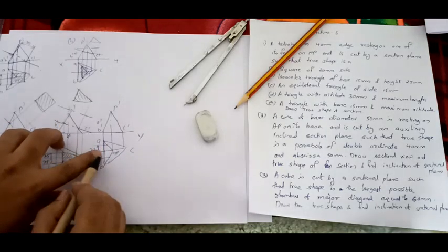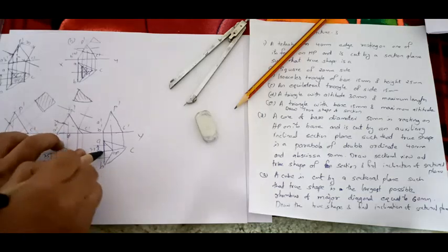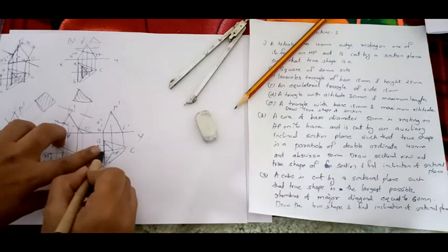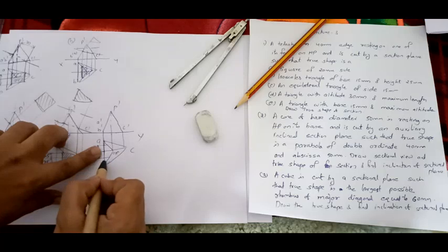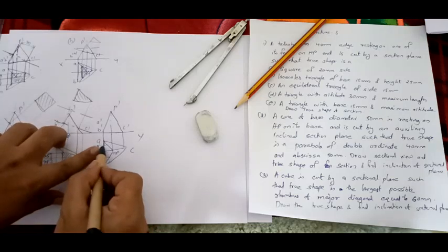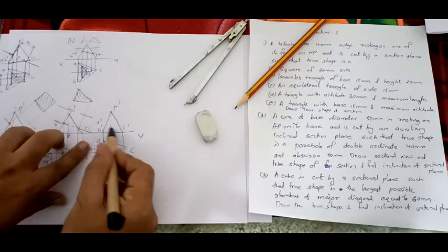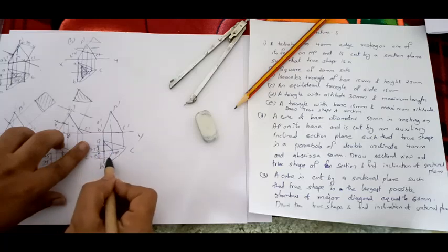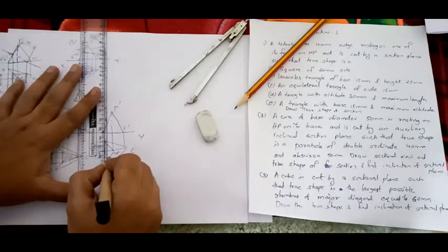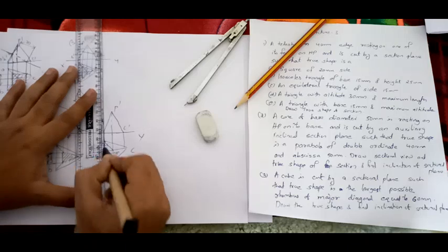That's the central line. So from this point, it is cutting here. It is cutting here, right? From this point on the scale mark 7.5 mm towards both the ends. Then from here draw a line parallel to XY line in order to touch these faces. Now this will be 15 mm, right? This will be 15 mm.